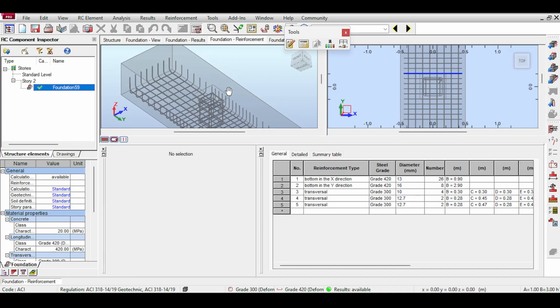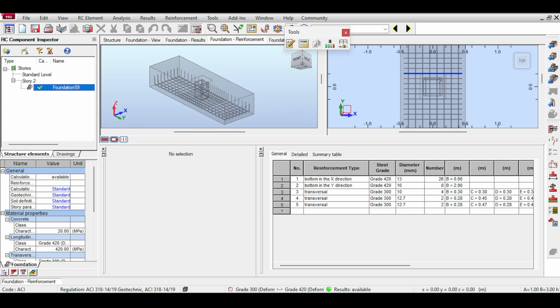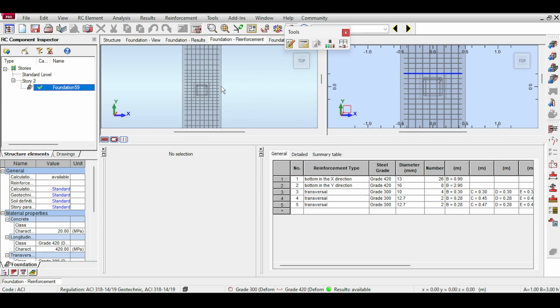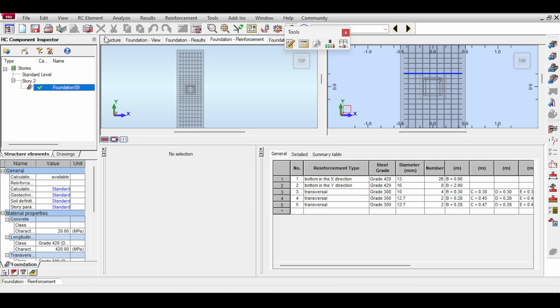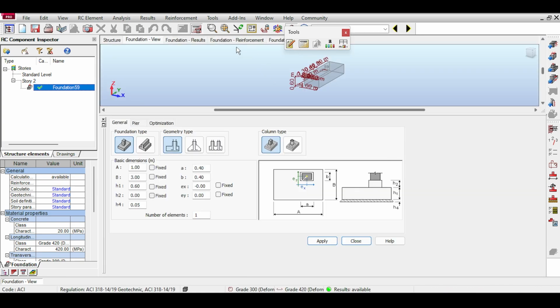You can see that there is, now I forgot exactly what the ACI code article was, but remember it's very clearly saying that if you have a rectangular foundation, then you have to increase the number of bars in the middle third and space them out in the outer thirds. It's been a long time since I have done this by hand, but just to mention that Autodesk Robot knows that this detailing trick exists and it does it for you, which is once again why software is amazing.